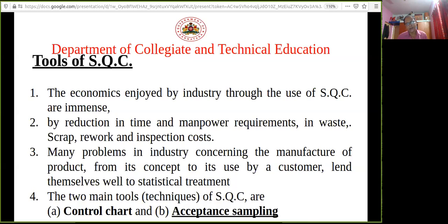You know that in mass production, one machine will give, say, 100 to 200 items per hour, and it is not possible for the inspector to inspect all 100 or 200 items in a span of 1 hour. So there is an acceptance number, an agreement that takes place between the customer and the producer, where they decide, out of a lot of 100 or 200 products, how to go for the inspection.